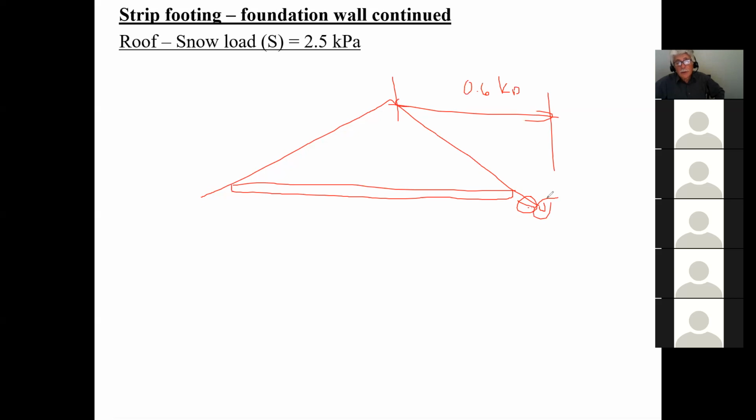Okay. Got it. And don't forget, guys, for footings, we have a factor of safety of 3 for QA, right? If I overlook this gutter, what do you think is going to happen to my QA? Nothing really. Exactly. So guys, worry about calculating your snow loads correctly. Worry about estimating your dead loads approximately. Don't worry about these little details because, you know, like for example, let me go back.